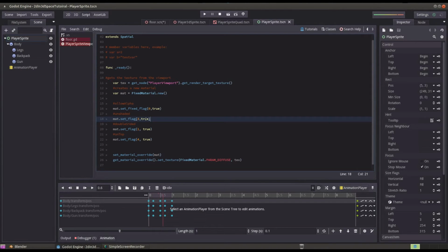There are some ways you can fix that, and I don't know why it does that, but that's the case. So when it's flipped, if it's not double-sided, you won't see the back side because of the way normal mapping works. It wouldn't show through. It'd just be transparent, so it looks like it's messed up. This took me a long time to figure out. Again, I don't know if it's a bug or if it's the way it's supposed to be, but whatever it is, you have to have the double-sided. And then finally, I added this on top. This one's not required, but it does help.